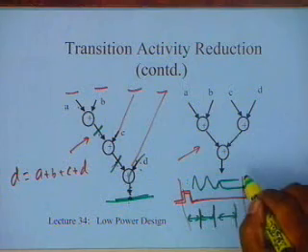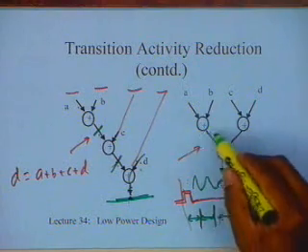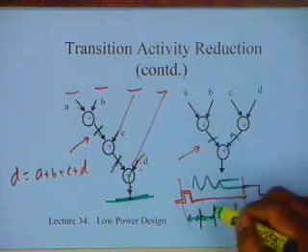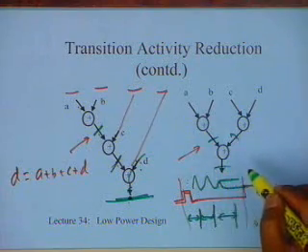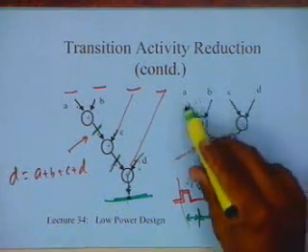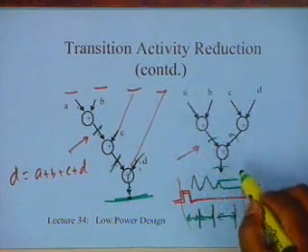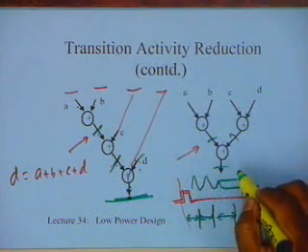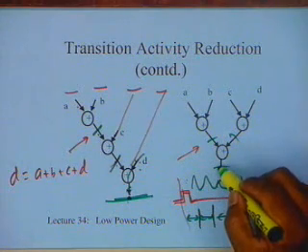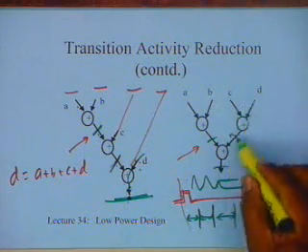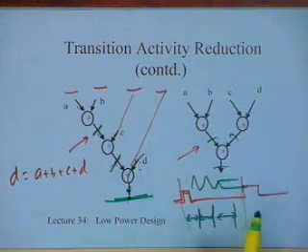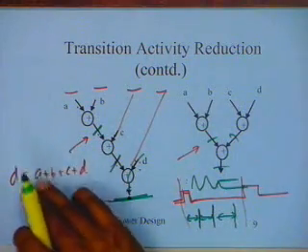Whereas if you look at this, there will be some value present over here, because of that an output will come, but the next output will be A plus B, C plus D, because these path lengths are more or less equal. So the changes that occur over here depend upon the variation in the path lengths, and so one of the techniques that is done is reduction in variation in path lengths.